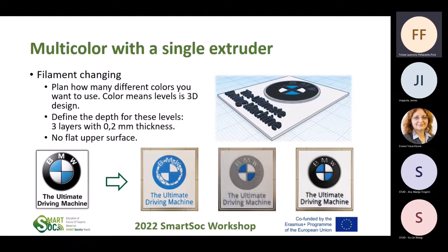There are slicer softwares where you can control very strictly that, okay, here I don't want to use it, here I would like to use it, although the slicing software doesn't recommend it, but I would like to use it here because I think that this is a risky place. So in the slicer software, you will have the option to tell the software whether or where you would like to have support structure.